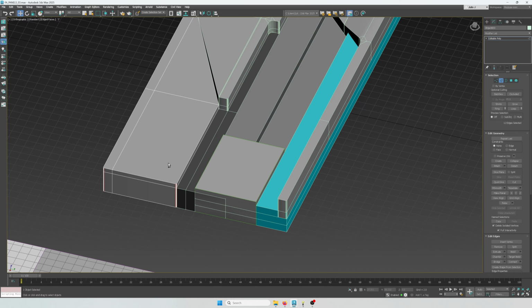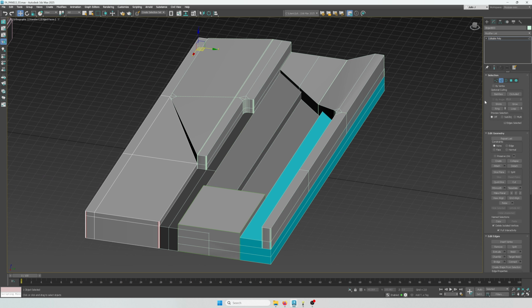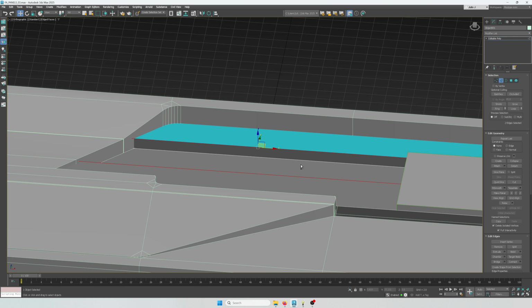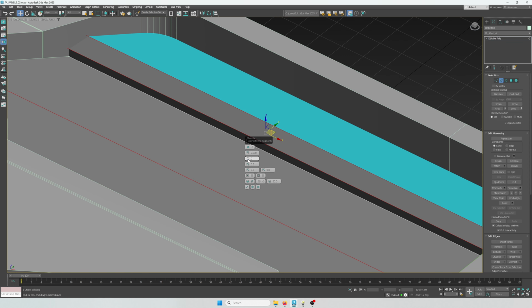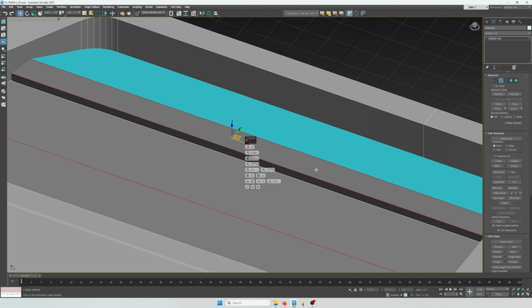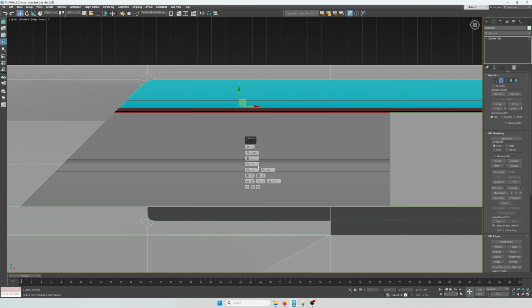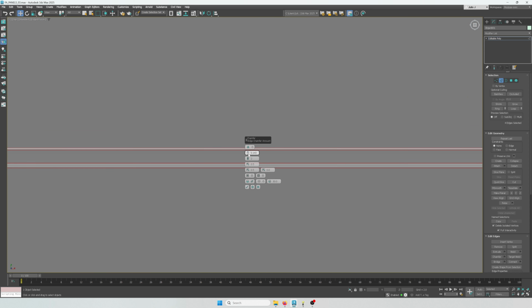One of the areas that needs more detail is the area that's in the center. Right now, everything is flat. So let's select the edges and the topmost area in that center. And then we can add a chamfer, but remove the segments. It's essentially creating a bevel in that area. And with those edges still selected, let's introduce a chamfer to create more segments. This way, when we bake down our normal, we're not going to have harsh polygonal lines.